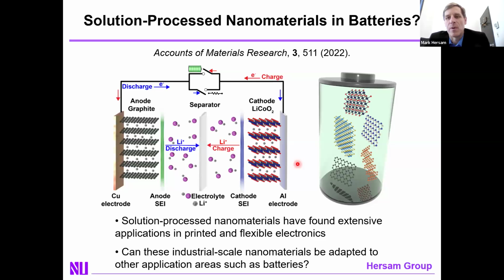but what caught our eye when we were looking at this initially was none of those components, but rather these two layers here, the so-called solid electrolyte interface, which is a layer that builds up due to unwanted chemistry at the electrode-electrolyte interface, and this will build up and grow as the battery is cycled. And the buildup of the SEI is one of the reasons that you see capacity fade in a rechargeable lithium-ion battery.